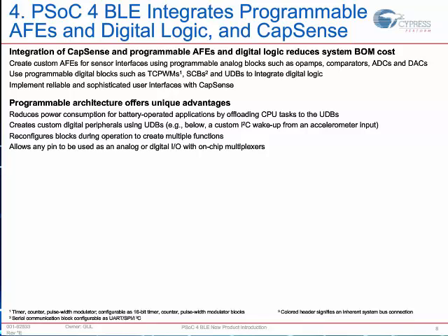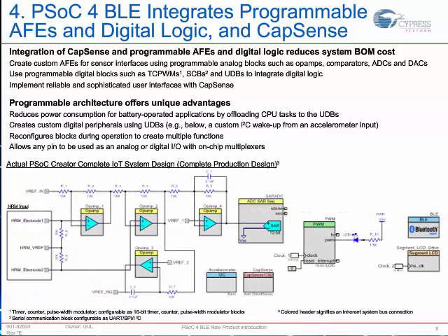And this screenshot here below that I just pulled is a screenshot from PSoC Creator of the schematic, and it shows you how, using the single PSoC for BLE chip, we've been able to construct an entire heart rate monitoring product. Starting from the left, you see your electrodes for a heart rate monitor coming in, going into my analog front end, which is constructed using 4 op-amps and an analog to digital converter.